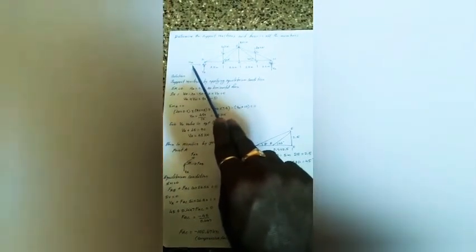Next, we are going to find the forces in each member by using the joint method. First, we are going to take joint A. At point A, we have two members, AC and AB, and one reaction force. We know that the horizontal reaction force is 0, so only the vertical reaction force is considered at joint A. These are the forces acting over joint A: FAC, FAB and the reaction force VA.